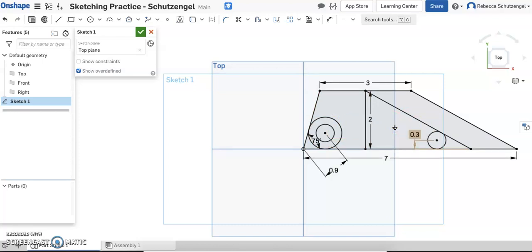Right. So just a few more constraints that I want to demonstrate. I'm going to draw another line, and I'm going to connect that line to the midpoint of this line. So remember, search for the square. That's going to be the midpoint of the line. And then as I'm drawing my line, I can draw it sort of out at whatever random angle. So there's no particular constraint on it right now.